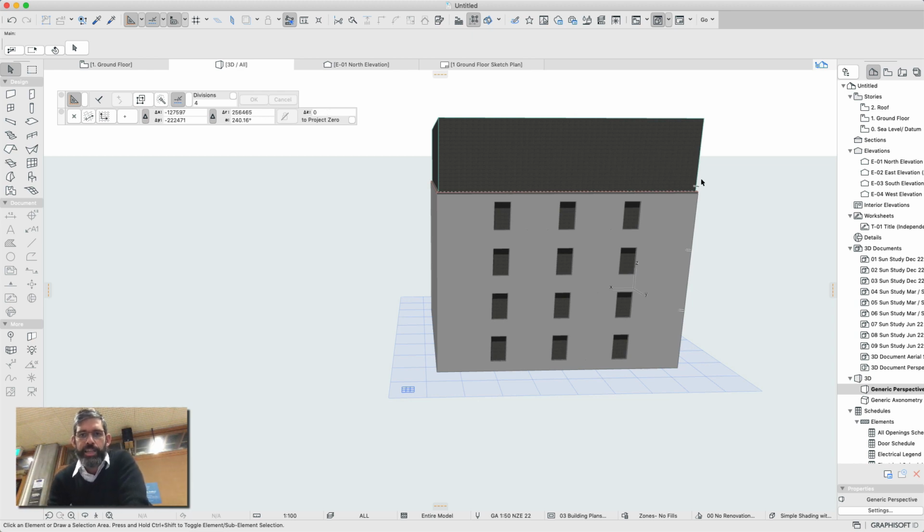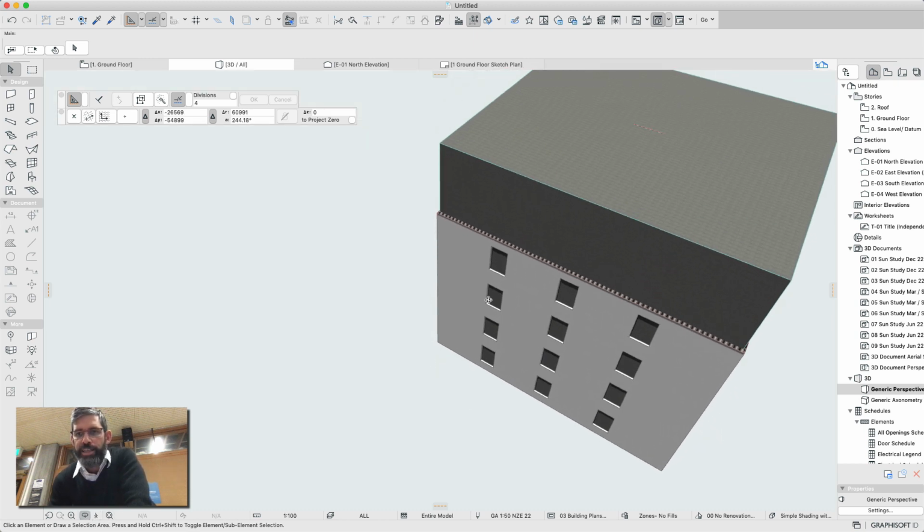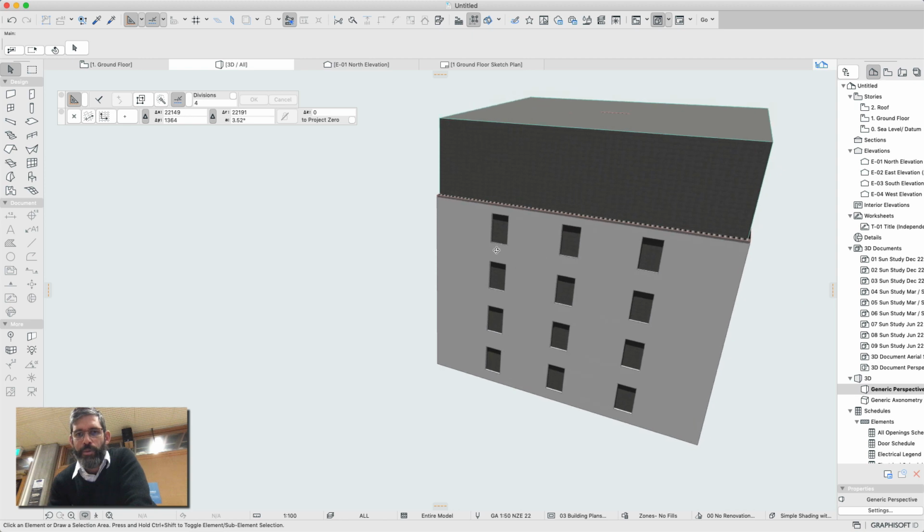All right. Okay, so what I've essentially got now is a great big block, and now you can see what we're trying to achieve here. See how the windows go in, and then they're filled. But obviously, I've also gone across the top of my roof, so we need to do a Boolean operation. Do you guys know what Boolean operations are? Or solid element operations, it's called in here. We're going to subtract the top of this block off and fit it inside the roof.